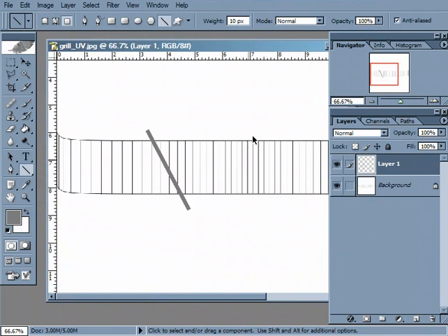That's not bad. Okay, so I'm going to set the line weight to 10, and I also want to make sure that this button right here, fill pixels, is turned on. What that'll do is make sure that it actually generates pixels. With either of the other two selected, it's going to generate vector paths, which we really don't want. We want to make sure fill pixels is turned on. Okay, and what I'll do is just click and draw a line.